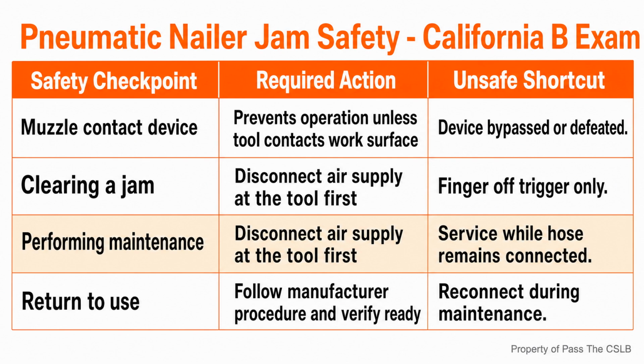I would look at the panel face, trace every perimeter, and inspect the accessible backside for shiners and missing blocking. I would pay special attention where the schedule becomes dense, because that is where wider framing or an engineered alternative may be required. I would document defects and hold the next layer of work until the correction is approved and completed. The central idea is still the same one I started with.